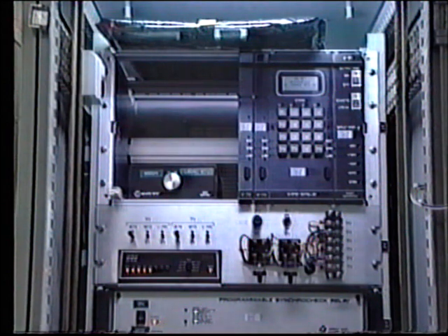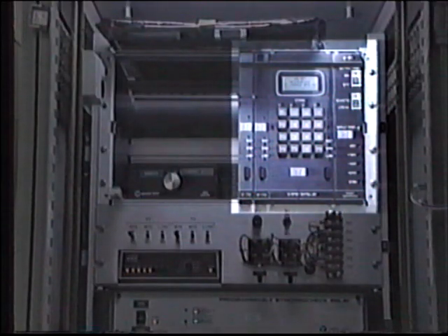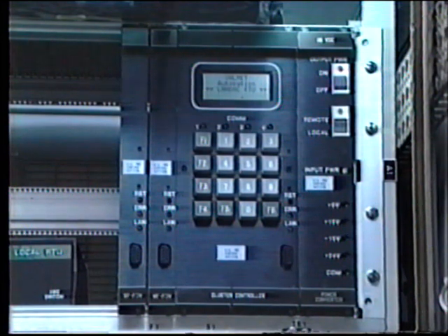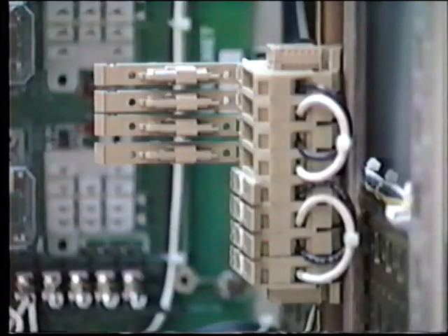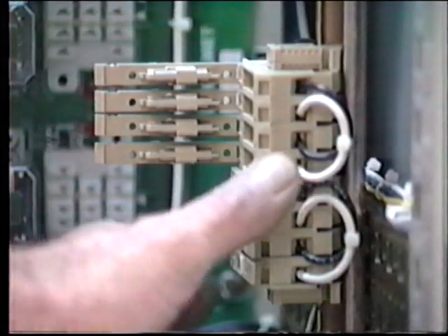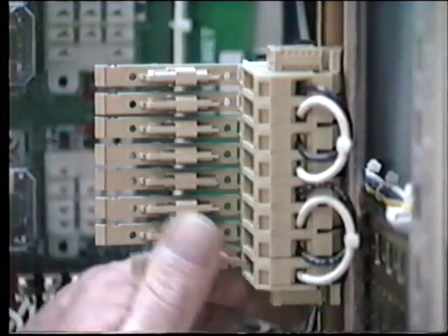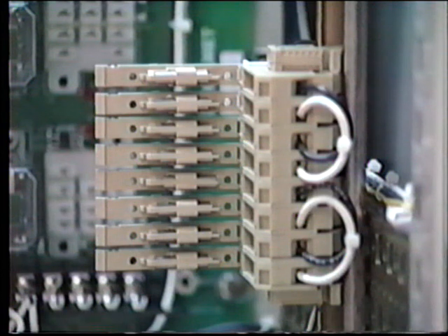A well-designed RTU should be provided with an interface to assist maintenance personnel in troubleshooting. This is often called a man-machine interface, or MMI. It should be equipped with indicating lights or other indications so as to help identify which components of the RTU are not functioning correctly. It should also allow for isolation of specific control outputs by a local remote switch or control disable switch. This will enable us to test sections of the RTU without tripping circuit breakers or other control functions.